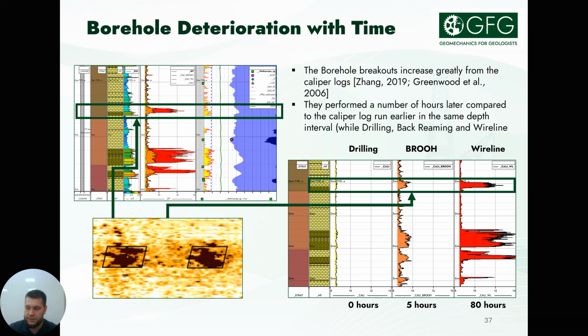Rock strain increases with time even under a constant loading stress. Therefore, when subjected to a constant stress even smaller than the rock strength, rock deforms and may eventually fail over time due to creep. This effect must be taken into account already at the stage of analyzing the geomechanical initial data.